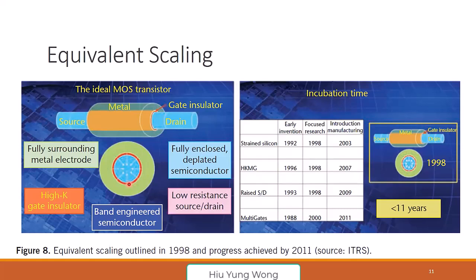So now, although the gate length does not scale as fast, because we use this new transistor, metal electrode, high K dielectric, band structure engineering using stress, and low contact resistance, the result is the same as making the gate length smaller. Okay, so you see that there are 4 different things. Strained silicon, they did that already in 2003.